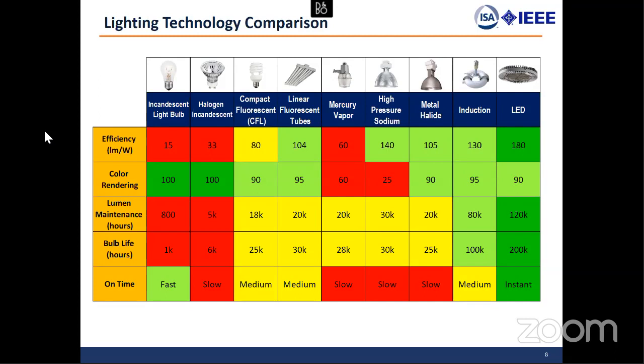Right. Because of the same lumens, you might use half, and you might have double the foot candles of some lights on the floor. So take a 400 watt metal halide high bay hanging up there. It's 24,000 mean lumens. You could use a 12,000 lumen LED light source, and you're still going to think it's better light. Yep.